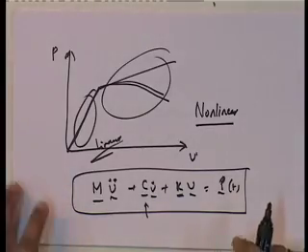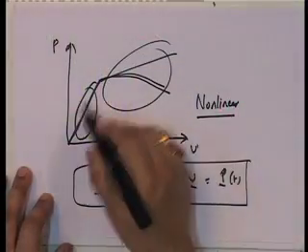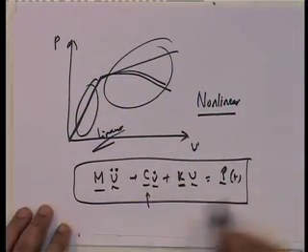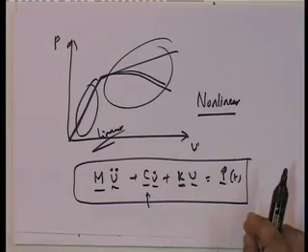I need to have a C which is consistent with my definition that I have used in the linear part, mode superposition. In mode superposition, what did I say? I said, well, take xi in all the modes that I am going to consider, and then my C matrix has to be consistent with that, because let us put it this way, since you have linear nonlinear, at least in the linear part, this solution has to be consistent with the mode superposition method. You understand my point?